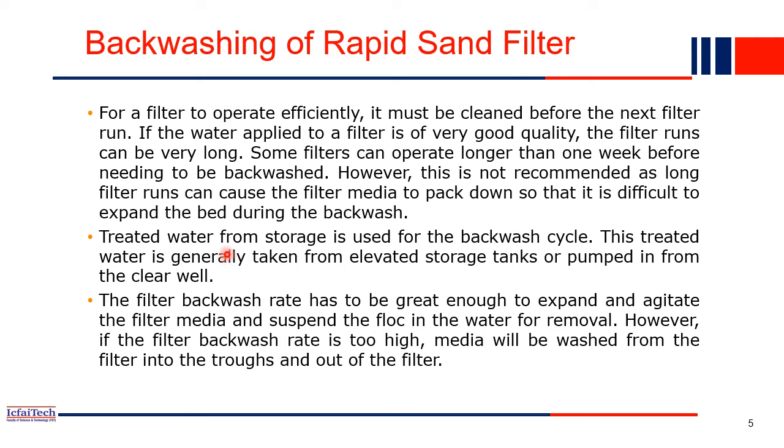Now treated water is basically used for the backwashing. Whatever treated water we have collected, a small quantity of this clean water is used for the backwash cycle, right? Now the filter backwash rate has to be great enough to expand the bed, because the particles are present in the filter medium, right?